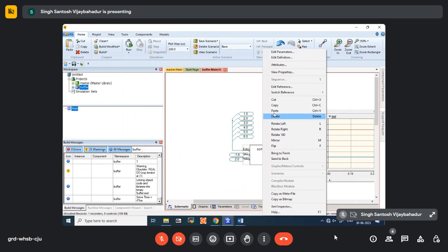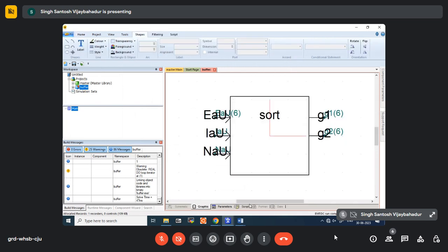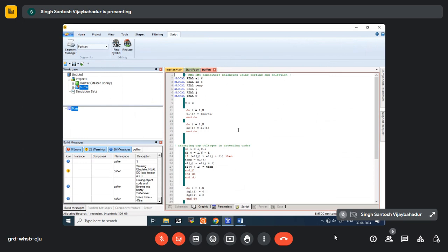The scripts you have done are in Fortran format, which is native to PSCAD. It becomes very easy if you already have an algorithm: you just run it and at every time step it will work. But there are also subroutine calls which you can write externally. For example, if you have something in C or later on MATLAB or whatever you want, you can interface it with those routines. In the help file it is available, as he has already mentioned. You can write any scheme and interface it appropriately.